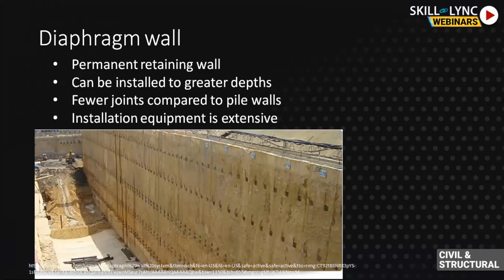Bottom up can be either a permanent or a temporary solution. Generally for temporary cases, it is fully excavated through different levels of propped struts or anchors. Then the bottom of the excavation is reached. From there, the permanent structure is constructed from the base slab level to the top.